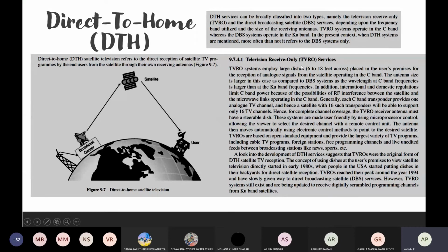So if you want a wide variety of channels, you need to be in communication with several geostationary satellites. Therefore, the antenna on that should be steerable. Okay, steerable is like a steerable dish. You can tilt the position of that dish in order to talk with another satellite. If you want to receive some other channels, you have to position it for that particular satellite.